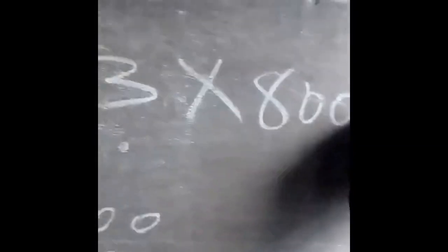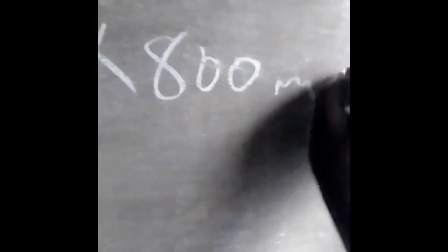Now we go back to the calculation: 13 stirrups times 800 millimeter, times the total number of pillars on that stage. Remember, it's from ground floor to first floor. We want to calculate the stirrups for the ground floor. How many pillars? 1, 2, 3, 4, 5, 6, 7, 8. So 13 times 800 times 8 pillars. Let's use our calculator.